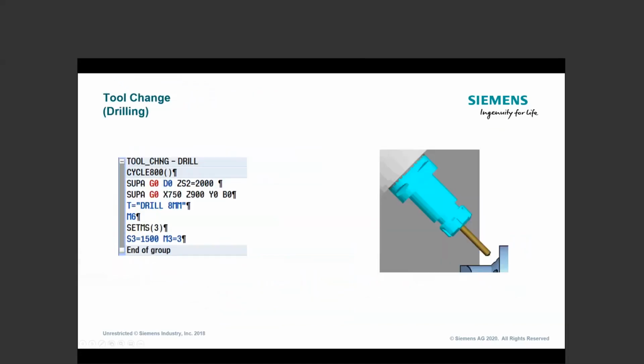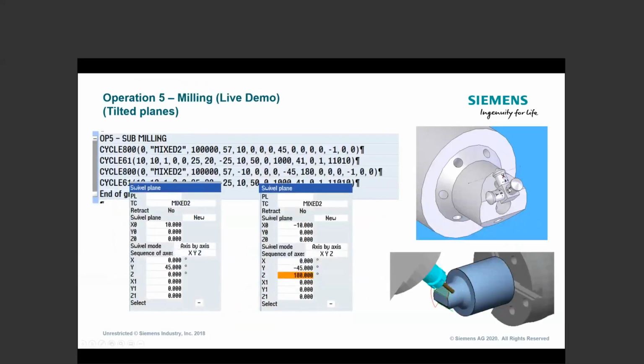We have this plane, and now the machine is moving relative to this plane. There is no way to suppress this, even in a rapid move. It's going to want to move relative to this plane. So you're going to want to take that into account for your approach and retract. You'll think, I can just do a Z over and it's going to come in the top. No, a Z move at a 45-degree angle is moving relative to this plane.